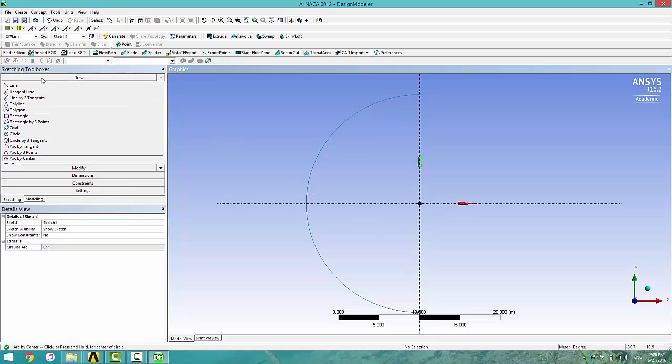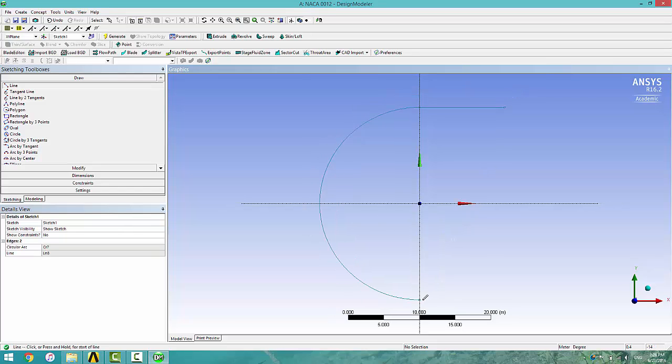Now you want to create a line. Make sure you see P again and click when you see the H over the line. Do the same thing here. Try keeping approximately the same size as the first one. Right here is okay.